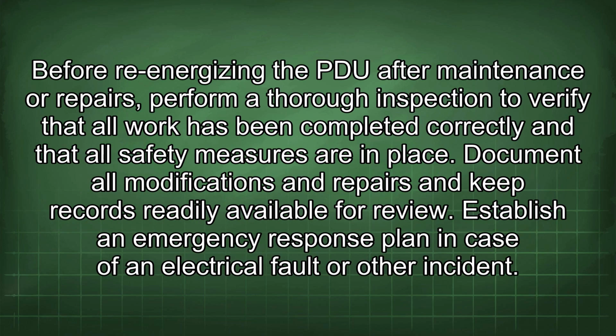Before re-energizing the PDU after maintenance or repairs, perform a thorough inspection to verify that all work has been completed correctly and that all safety measures are in place. Document all modifications and repairs and keep records readily available for review.